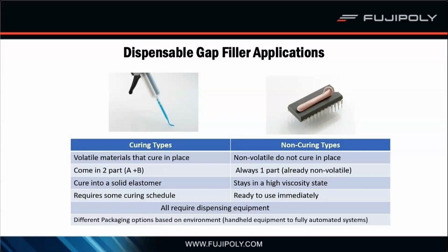Of course, non-curing types, as the name implies, stay in a viscous state. Since these do not cure, some customers do have concerns about reliability. These types of materials are designed to have higher viscosity and thixotropic characteristics just to ensure that the material does not migrate from the interface. Suppliers often suggest things like a max gap just to reduce the risk of pump out or migration of the material. With all materials, you'll want to review and evaluate the durability and test data that suppliers provide.